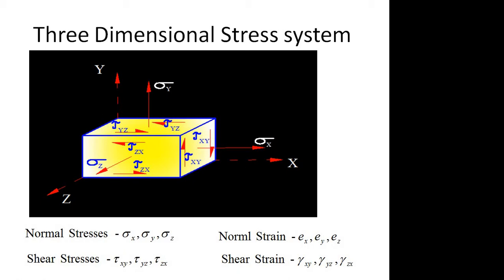So even though we are applying stress along only one direction, as we have discussed in the earlier classes, when we apply a load in one direction, in the other two perpendicular axes, if elongation happens along the x direction, compression happens along the y and z directions. That is, lateral strain occurs in the other two directions.